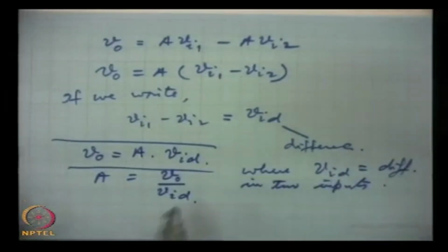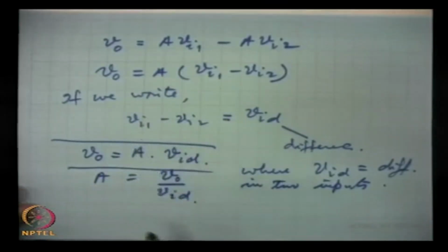So this is a very important analysis, and it has brought out several important features of the differential amplifier: it acts as a differential amplifier, plus there are two inputs, one inverting and the other non-inverting. Then we take another parameter from this AC analysis, and that is input impedance. For every amplifier, input impedance is a very important parameter.